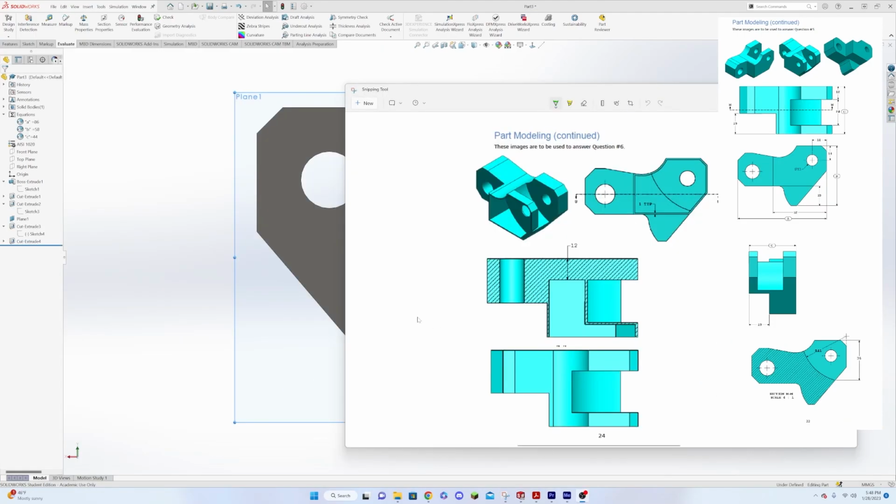So for the final step of this piece in the exam, you can see that we're going to be cutting out these shells here. And you can see here that they're calling out for some cutouts here. And so in your alphabet of lines video, you would have seen what these cutouts were, what these lines meant. And this is showing that there's going to be a cut that goes right down the middle here, right? And you're looking at a half section here. And these lines here are showing you that this is internal material that you're seeing here.